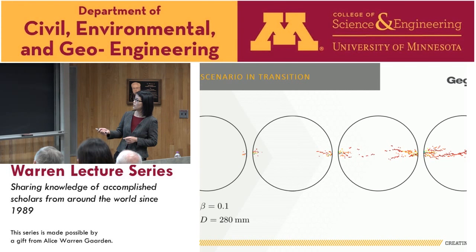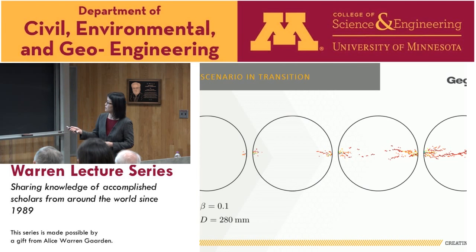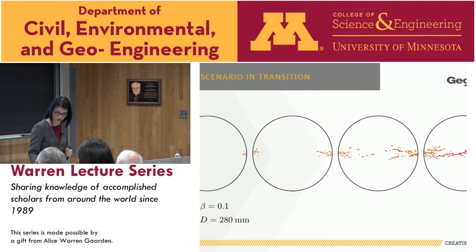That is where you have those microcracks starting from the edge, from the top and bottom, but the center crack also more or less develops at the same time, together with these microcracks. That's perhaps the most interesting case, because if the failure mechanism is like this, that's the case that gives you the most accurate tensile strength prediction.